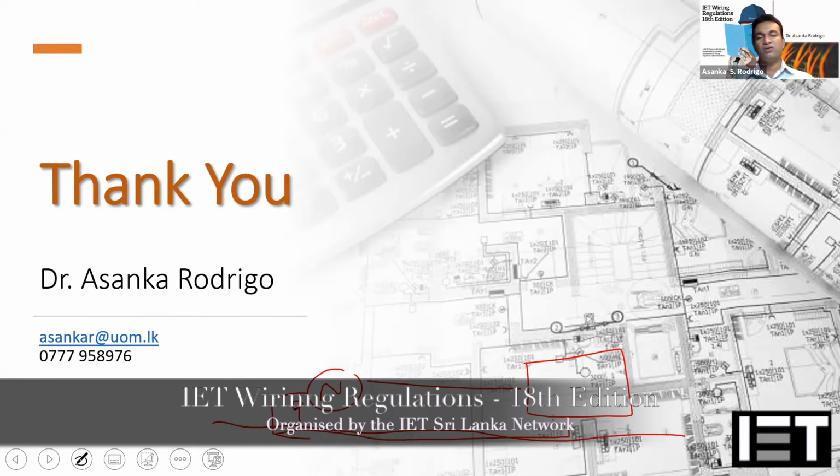Other than that, you don't need an earthing system, or you don't need the earth, because if you can create this type of closed loop, even if there is a certain abnormal current, that will go through the closed loop, so that you can detect it and isolate the system if there is anything. Now in here you can see no current goes to the earthing, the grounding system, or what we call IG, the grounding current, is 0.